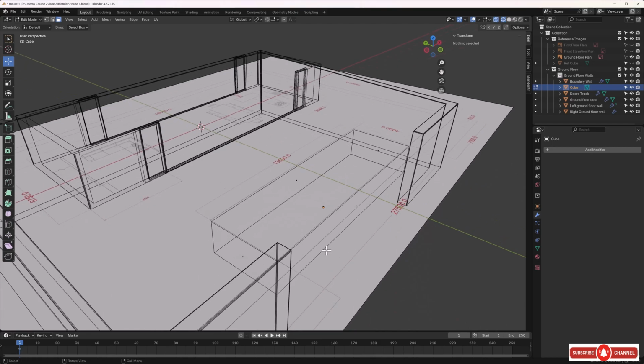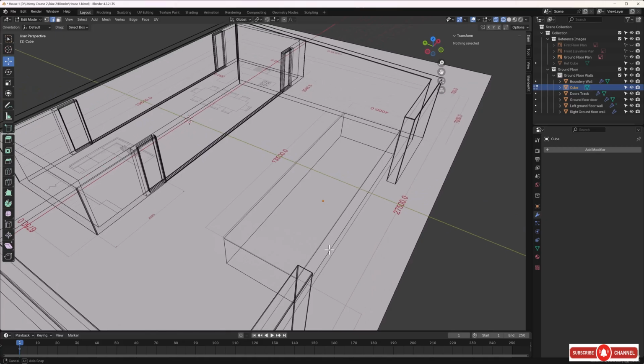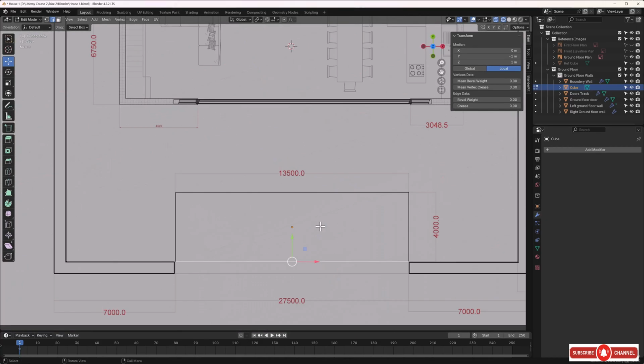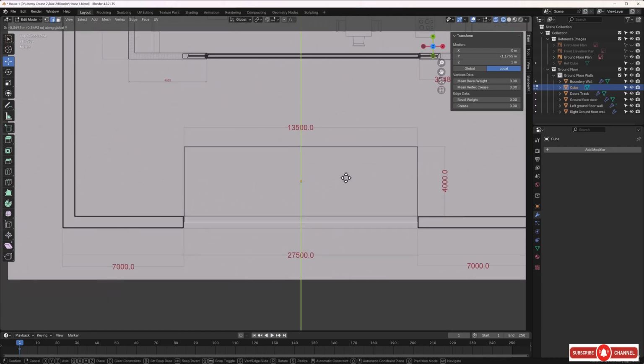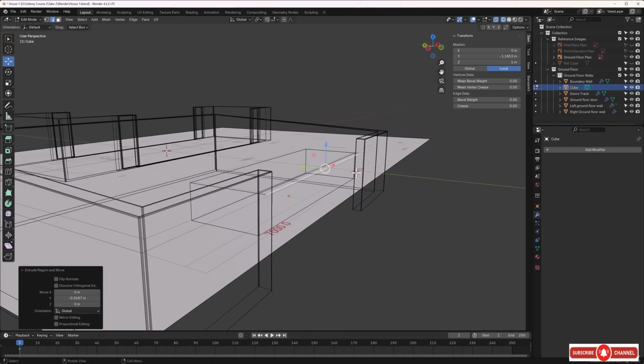And I think now, let's press 2 on our keyboard so we can select faces. And maybe we can grab this top face here. Let's press 7. And let's press E for extrude, and Y, and bring this over slightly to about halfway across the wall like that. And now let's press E again and Z and bring this down now to create that infinity drop that you see on some swimming pools. There we go. That's cool.